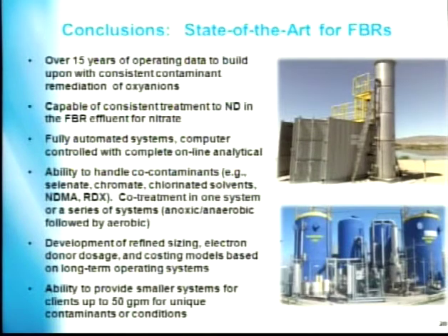And so what's coming off as residual TOC, the results we saw were still well below the 80-60 rule. But you also have the post-aeration, which has organisms that come off the FBR, which can then oxidize that residual TOC because they're facultative, meaning that they can live in an anoxic or aerobic environment, and they'll actually oxidize any residual TOC potentially there before it's chlorinated and creates disinfection byproducts.